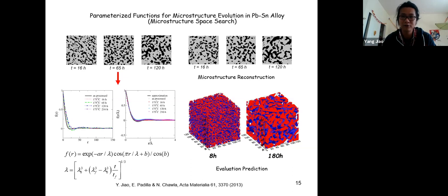And we show here that you can use the correlation function not just to randomly search the space, but you can correlate this with a processing process. We can use a correlation function to model the microstructural change during an aging process. So potentially, if from the optimization I determine this is the best microstructure, I can give you a time of aging, how long you keep the system at this temperature. So not only for 3D printing, but it can also be correlated with the actual processing of material.